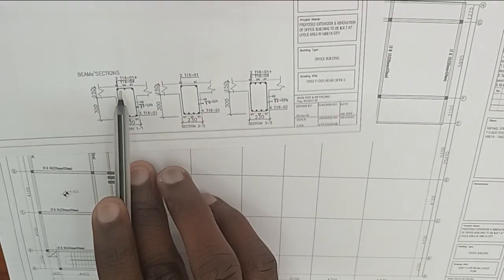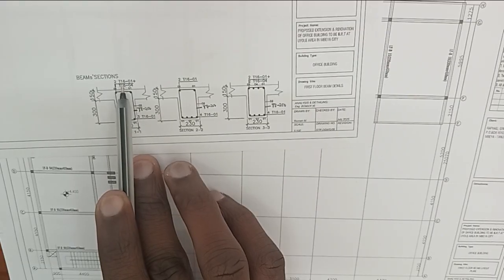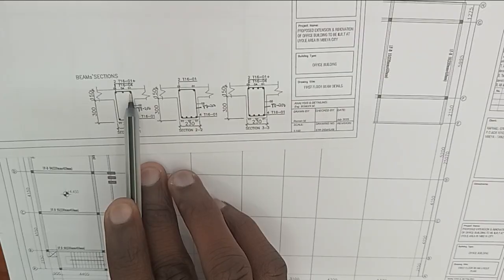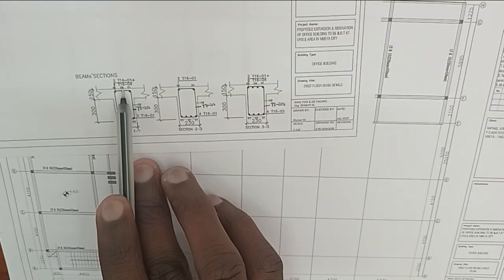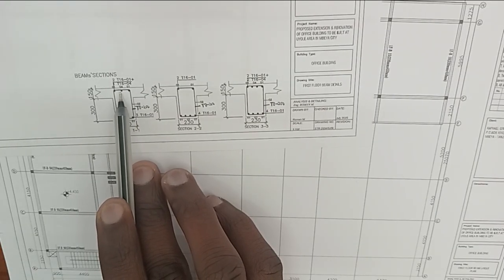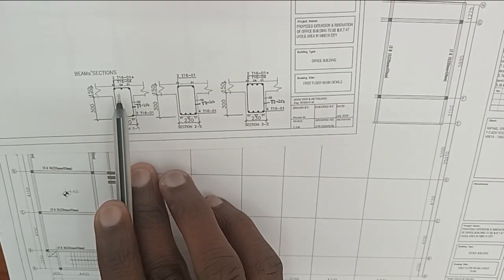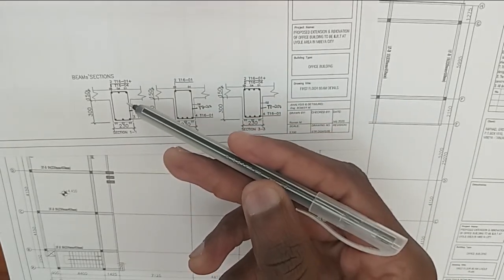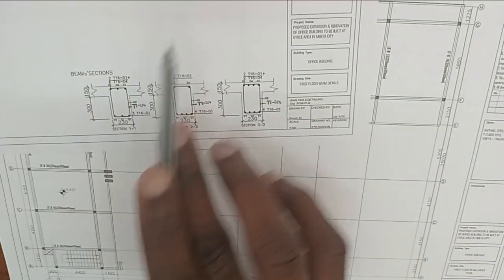And at the top, there should be two main bars with a diameter of 16 millimeter at bar mark number 1. So this is the first main bar, and this is the second main bar, and one extra bar of 16 millimeter at bar mark number 4. This extra bar is located over supports for negative moments. These extra bars are not provided over the whole length of the beam. Instead, they are provided only where additional strength is required.